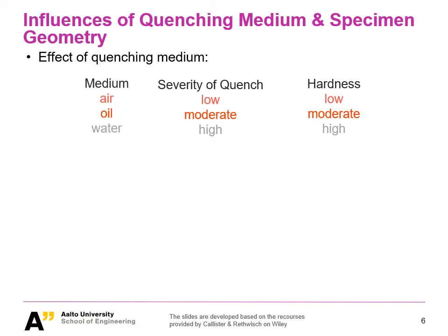The question is, how do you control this quenching, how do you control the cooling rate so that you can for sure get martensite, not touching a little bit the perlite or so? So that is something we need to discuss with respect to this cooling.